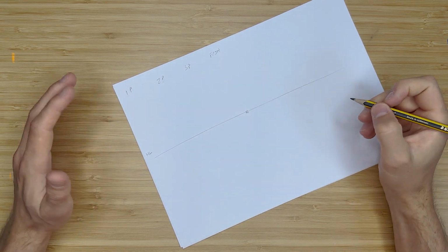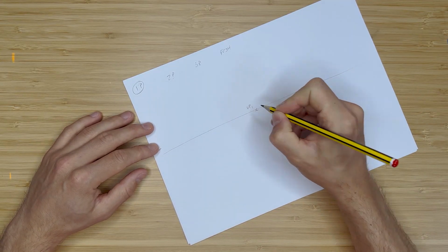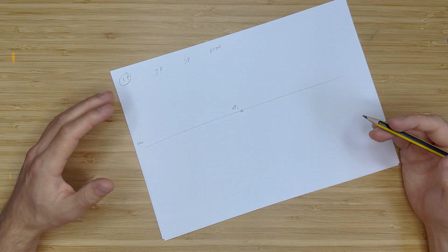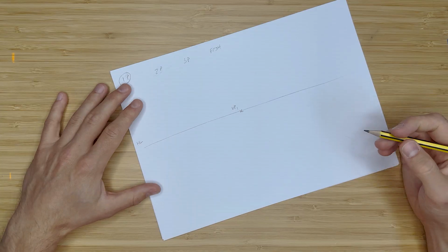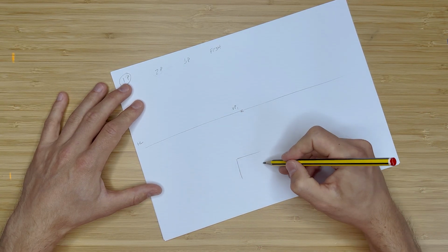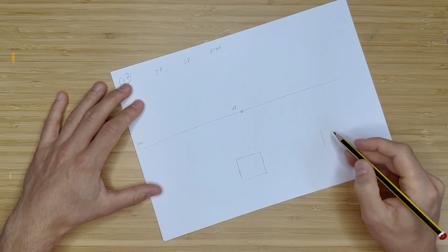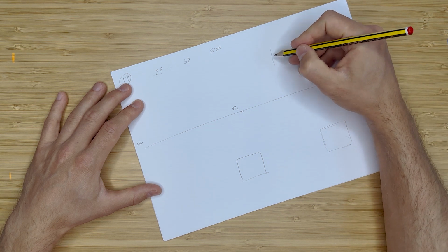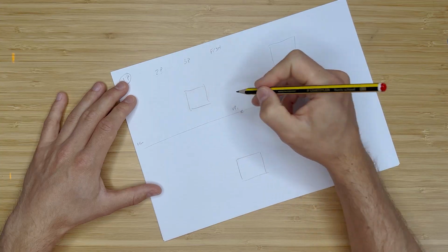So for this one, for a 1 point perspective, which is what we're going to look at now, we're going to have our vanishing point right in the middle. Okay, so we'll call that vanishing point 1. And for this example, we're going to use some cubes and cuboids, as we usually do, to show how 1 point perspective works. So all we're going to do is draw a very basic square. Let's go one here. Let's go one over here. Let's go one up here. And let's go one over here.